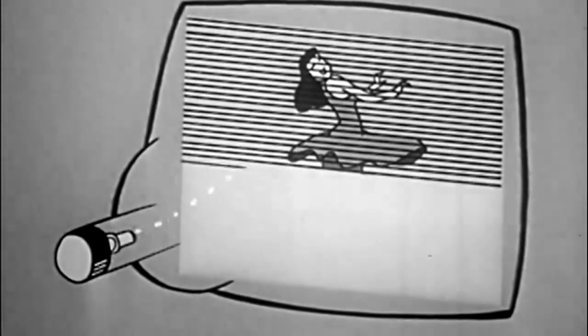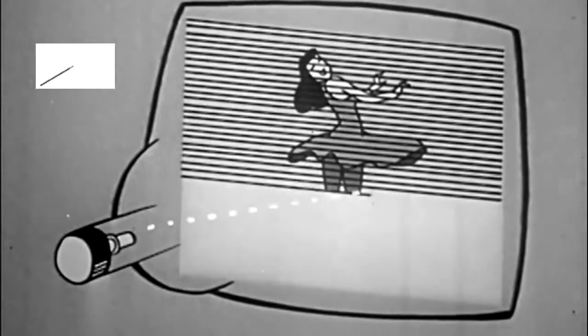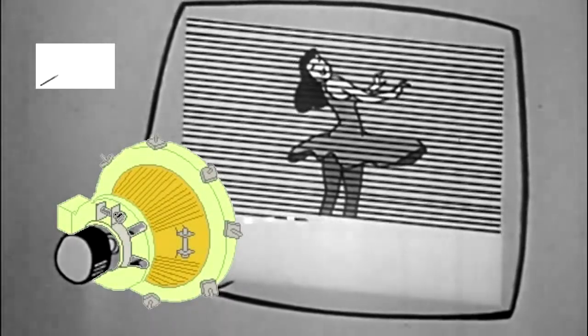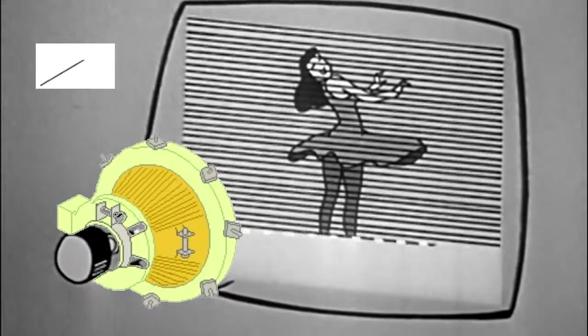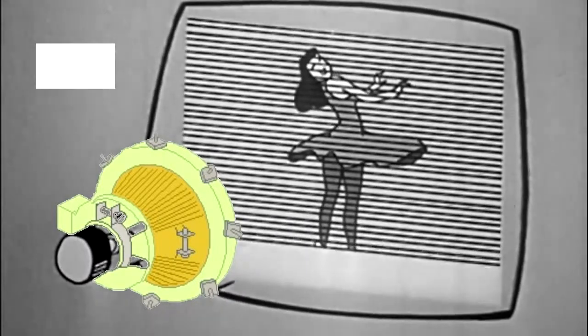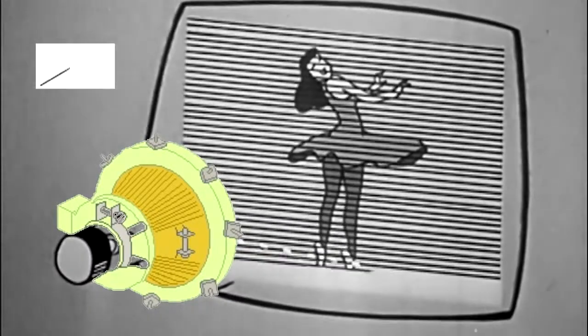The CRT had to then move the electron beam around to recreate the original picture frame. This was done using two coils of wire around the neck of the CRT. The camera has to tell the monitor where there is a dark or light portion of a picture, but it also has to tell the monitor when to start and stop producing each line of video, and also when to begin and end each field as well. That's the purpose of synchronizing signals. A group of special signals are sent by the camera to pass along this synchronizing information.